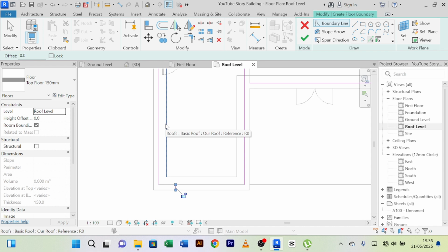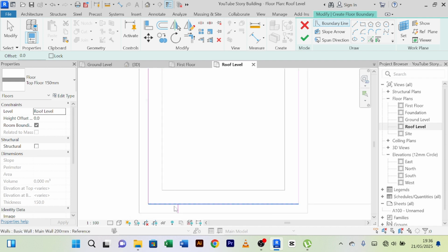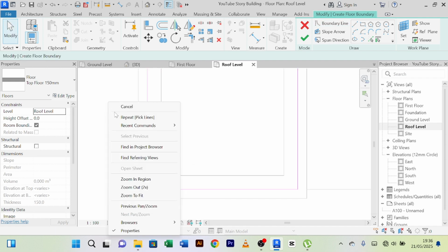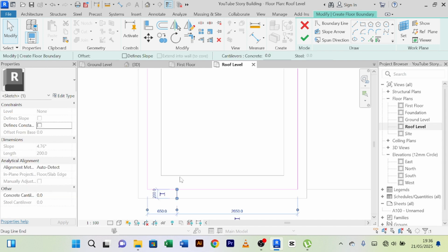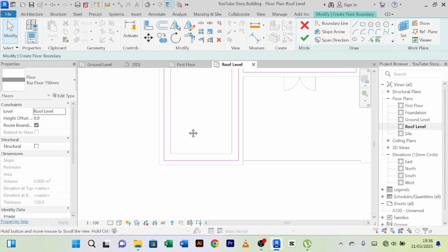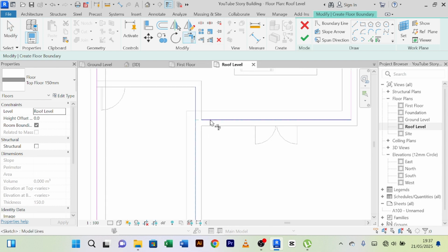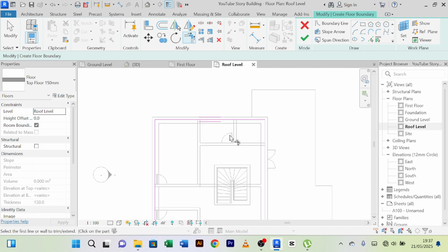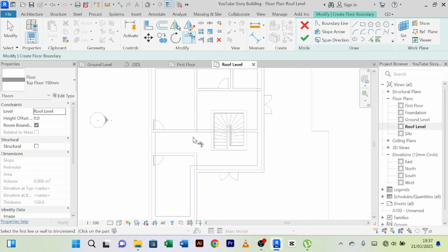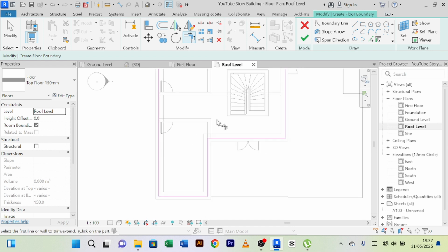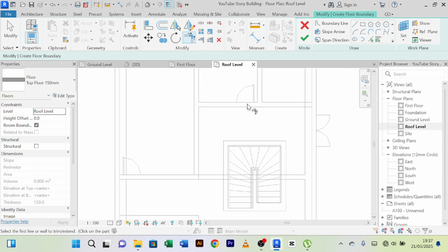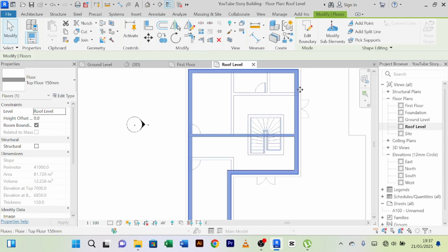That's not supposed to be there, but we shall delete it anyway. So now this one is an offcut. This one is an offcut. I will delete it. Then we need to trim and extend this to corners. We come to trim. We trim this and this. We look for others, okay. Yeah, others okay. So if you have done this, you just tick from here.